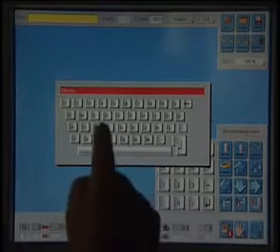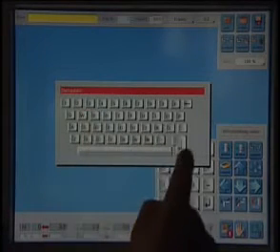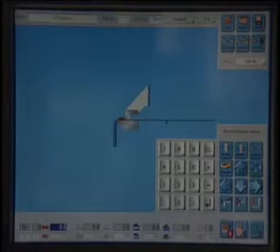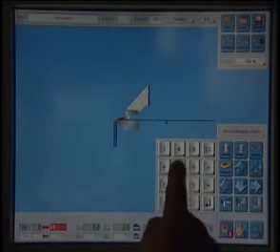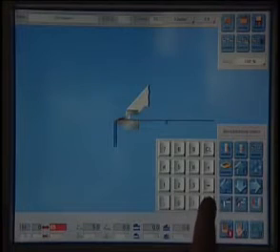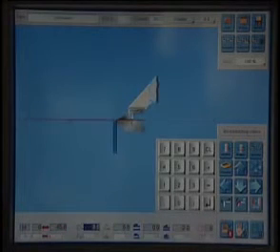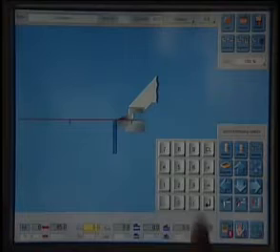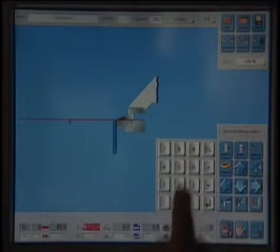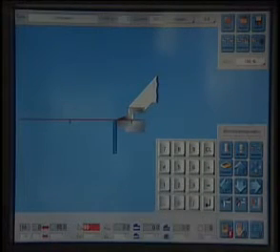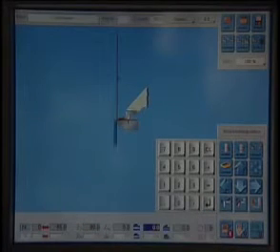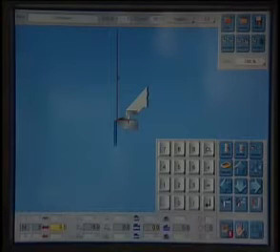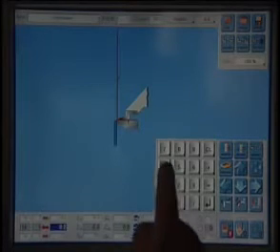Now we will show you how to program a panel for a facade. Let's start with the first backgauge position, and the profile will immediately change accordingly. After entering the bending angle, you will get a first impression of your profile on screen. As we do not need an additional lift-up of the upper beam, we go to the next line with the cursor down to enter the next backgauge value.